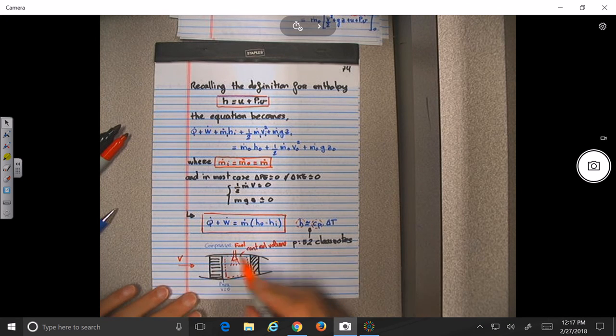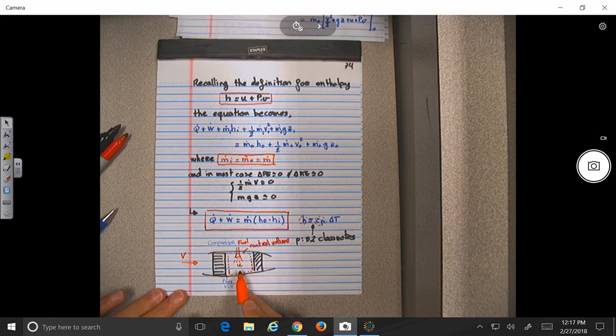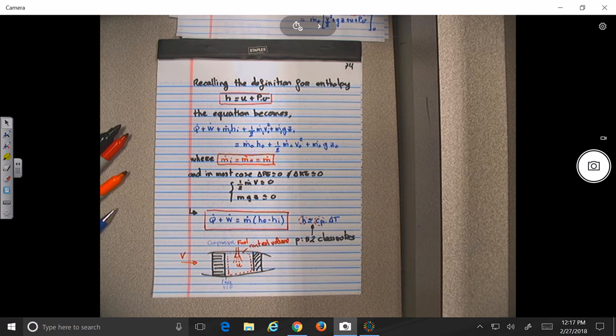So anyway, when you put the fuel, you put the spark, what are you doing inside the system? You are adding internal energy, no? Yeah, in the form of heat if you want. So now you have all that energy inside. You have transformed all the velocity of the flow, the kinetic energy that's coming inside the engine, into a very high pressure. Now you can use all that high pressure you have created to create work at constant volume. In addition to that, you add energy through internal energy by burning fuel. So now you have a bunch of energy inside here, no?